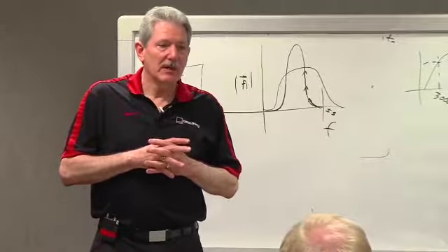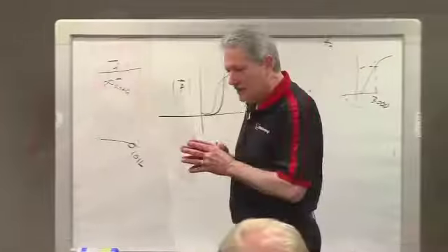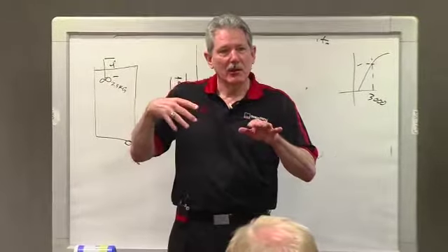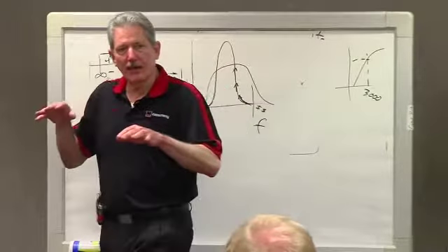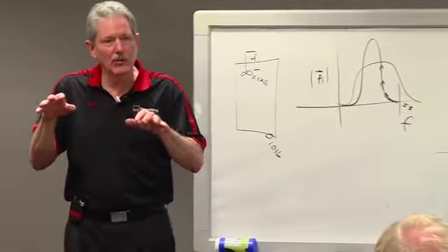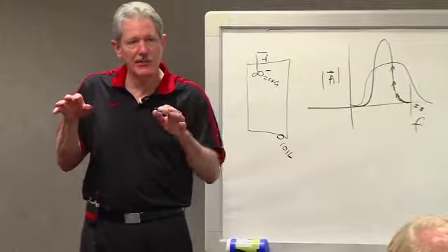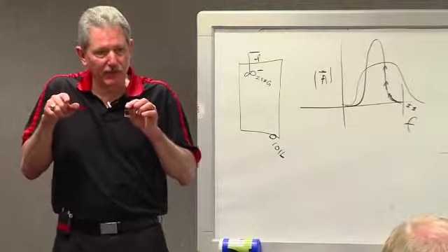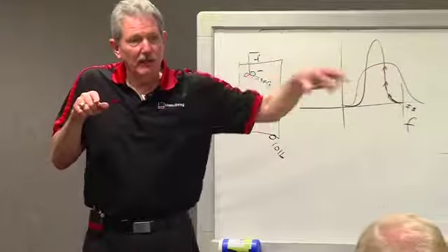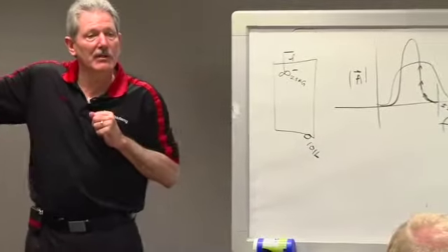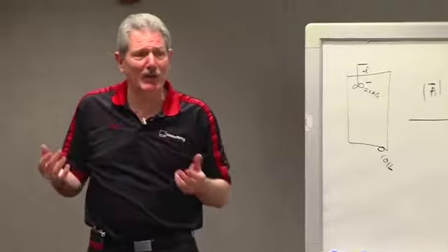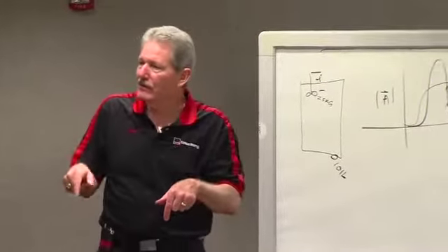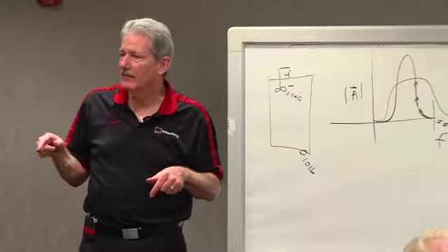That's the birth of load response control. Now that we had this regulator that was intelligent, we could monitor some things. All we did on the load response control is a real simple energy conversion. Instead of drawing energy in the form of kinetic energy from the engine, we drew it as potential energy from the battery. We've just spent all of our time putting energy into that battery. Let's just use it for that short time that we need it.